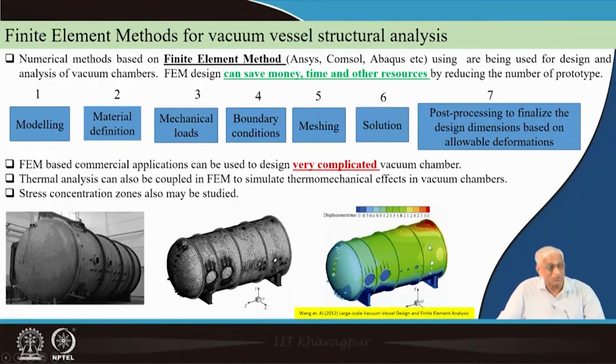But be careful to interpret the output. If you are not careful, you may be making a mistake, and even a very smart employee may suddenly get into trouble, particularly while dealing with mechanical structures, if he has made any mistake in boundary conditions or meshing or initial input parameters. And when you connect a vacuum pump, suddenly it may implode. So instead of impressing the boss, you may lose your job. One should be very careful when using computerized models for thickness calculations. But they are very user friendly. You can cross test them with your numerical methods using ASME codes.